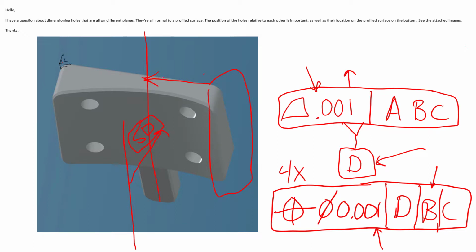Remember, how far centered is that axis to that datum C that we built there? Datum D doesn't really matter in this case that much, just because the curve will exist up or down. It's not really controlling anything, but you still may want to include it to A, B, C, just so that when they're doing the part setup, they lock it to datum B as well when they're inspecting this profile tolerance.